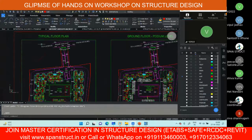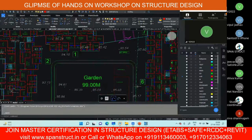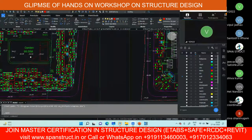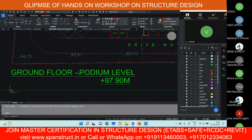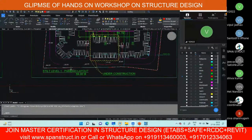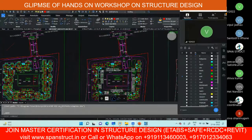This is a typical floor plan. Also there are a lot of towers here, like tower 3, 4, 5, 6, 7, 1, 2, and like that we are getting towers here. You can see that we have a ground floor, which we will call the podium level. And again, we have a stilt floor, which is a parking layout here. So like that, you will get an architectural plan. And this architectural plan has to be converted into a structural framing plan.